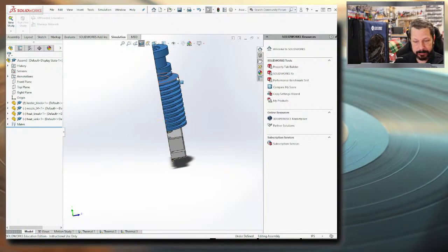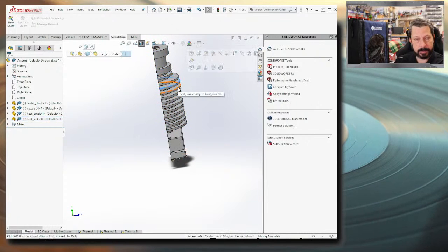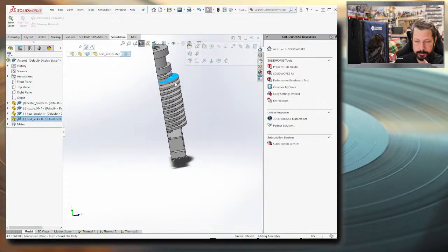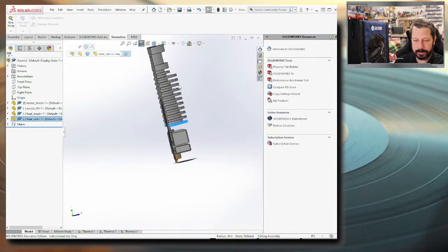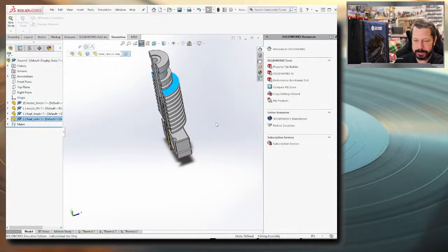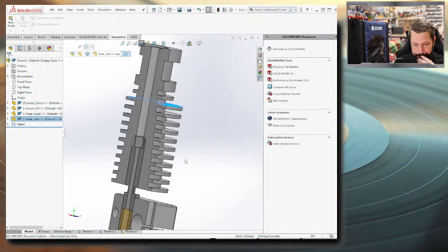You have convective cooling on these fins because there's air blowing across it. That's the fan that's always on, blowing air across this thing. When I do the simulation, I'm just going to use the flat surfaces, although technically it would be these surfaces also, but it's not worth going around trying to click all of those. I just use the flat surfaces in the model.